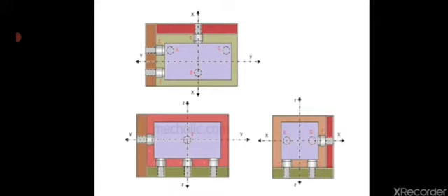2 more pins are inserted in the fixed body in a plane perpendicular to the plane containing those 3 pins. Now the workpiece can't rotate about the Z axis and also can't move toward the left. Hence the addition of these 2 pins restricts 3 more degrees of freedom.